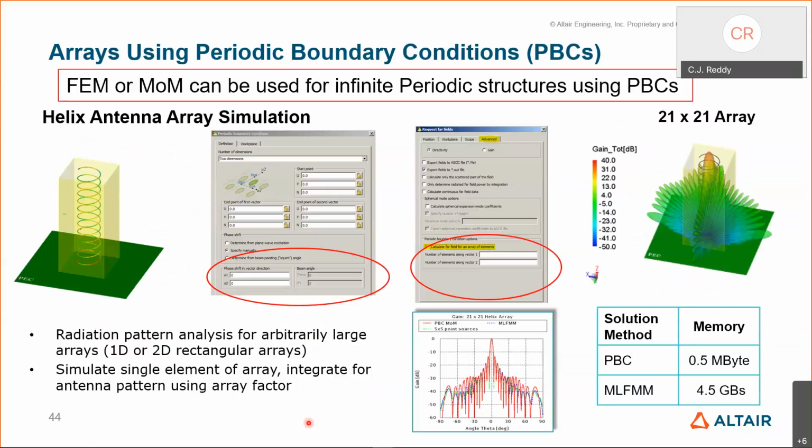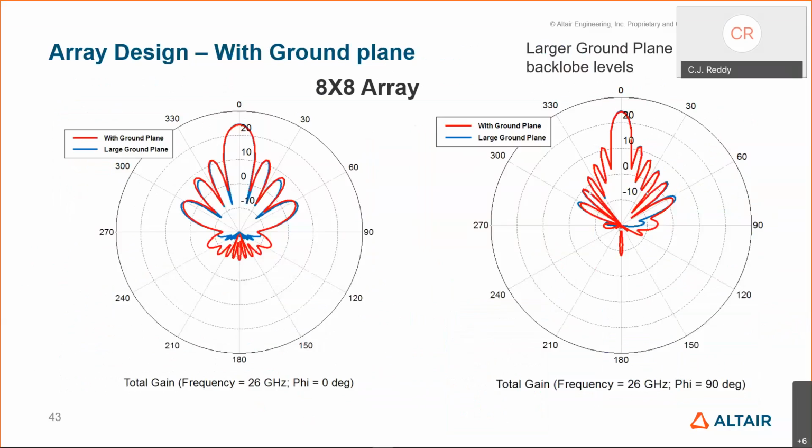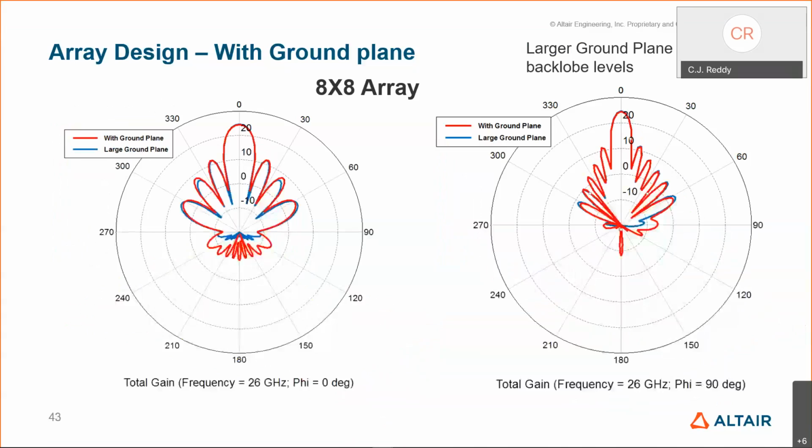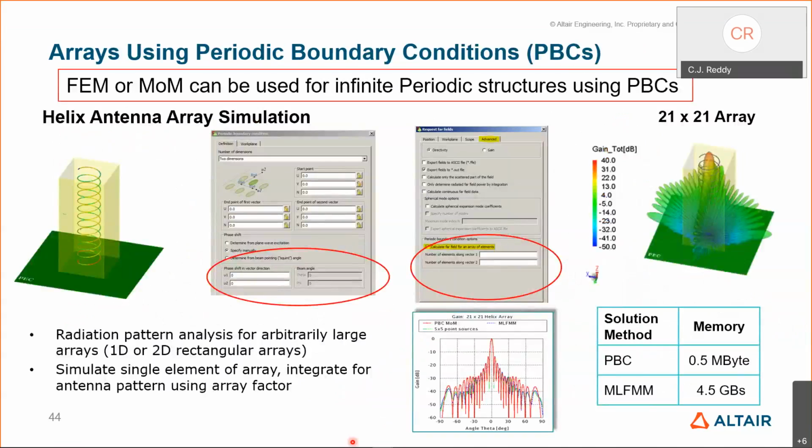You can also, because these simulations we have done as a complete, what we call a whole problem, meaning you apply MLFMM or you apply FEM to this problem and solve the whole problem. That could take some time and memory. So instead, one can also apply different techniques to solve them more efficiently. One of them is applying periodic boundary conditions.